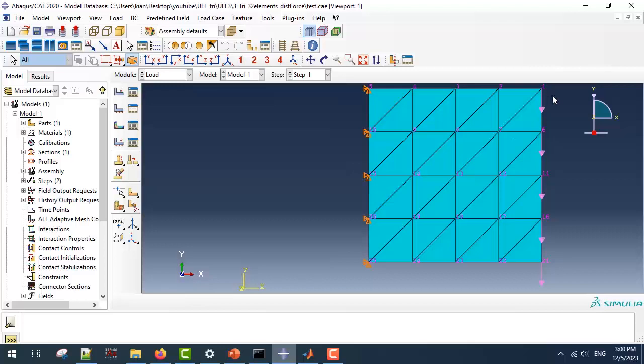Now we are going to use those point loads instead of this distributed load here. We are going to use a nodal set 6, 11, and 16 for our inside nodes, and a nodal set for nodes 1 and 21 for the different loads.